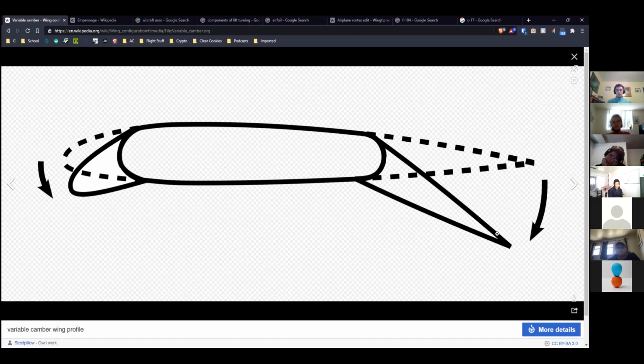A slat basically does the same thing because if you look at a whole bunch of airfoils, you'll notice that the more intense the camber is, the chord line actually goes outside the wing, because the leading edge is now here and the trailing edge is now here. So if you connect those with a straight line, the chord line is down here, whereas the camber line is still basically through the middle of all these. You can kind of tell where the camber line is because it's roughly halfway between the top and bottom surface everywhere.